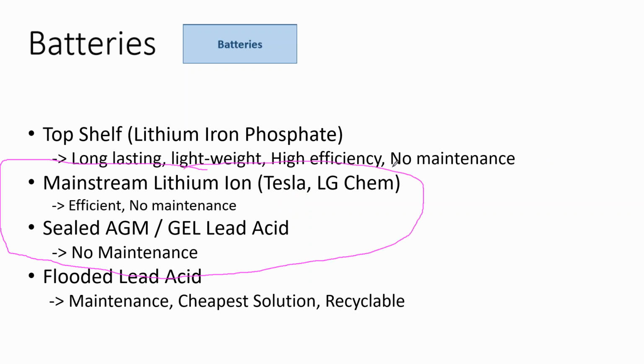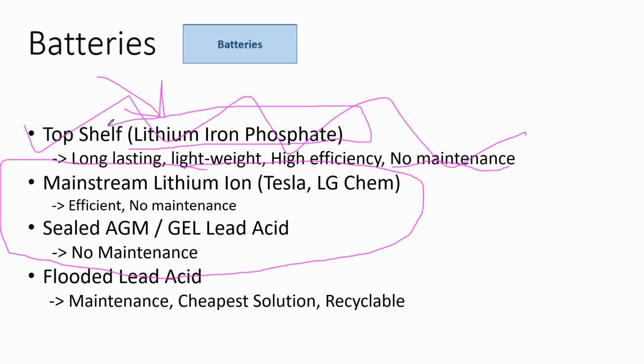There's something that's very unique about these two categories, even though they use different materials, and it's still true of the high end, but this is so expensive, you're usually not deciding between lithium iron phosphate and lithium ion. Usually you're going with lithium iron phosphate if either you have the money for the most amount of bling, or the application is either so small that you don't want to have to worry about it for 30 years, or so remote that the cost of maintenance is prohibitively expensive.